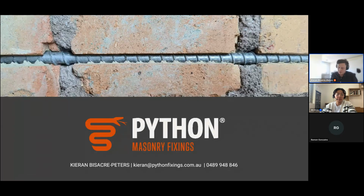However, with the original brick ties, they're completely untreated. Usually, they don't have any corrosion protection systems on them, hence all the corrosion that occurs. With our anchors specifically, they do have a very serious corrosion protection system on them, and so we expect them to last the life of these heritage structures and outlast most of the other elements.